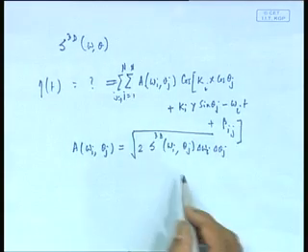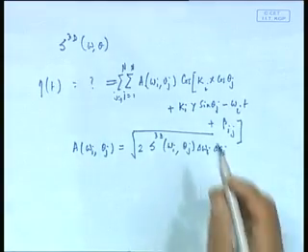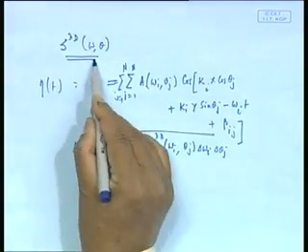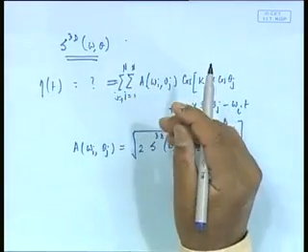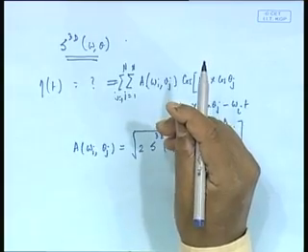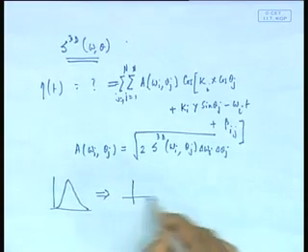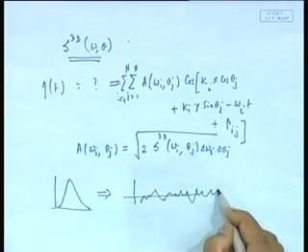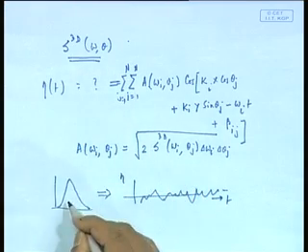See earlier, if you remember, I have this formula given, after all this formula is known to me now. So, I can find this, reconstruct a realistic realization of the ocean wave, reconstruct what should be the eta t, meaning a reverse problem. I have a spectrum here, in a 2D case I have the spectrum here, find out what would be, go from here to there.